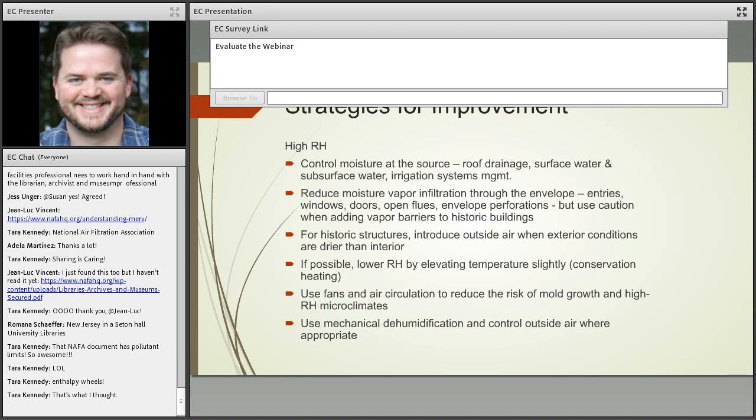It may just be the incoming outside or return air that is adding a little bit of heat to the surface of that wheel, then gets transferred back. It's kind of hard to talk through without a diagram, but there are a lot of heat transfer scenarios or designs where we're moving heat from the mixed air airstream over to the reheat side to save a little bit on mechanical. We basically bypass the heat around the cooling coil.